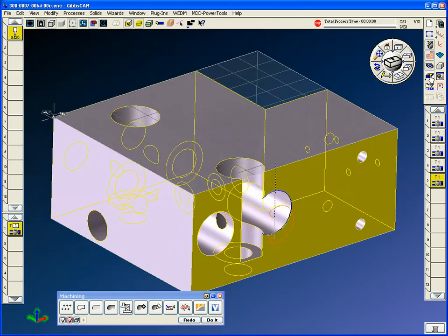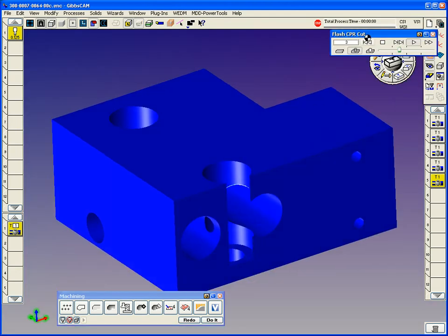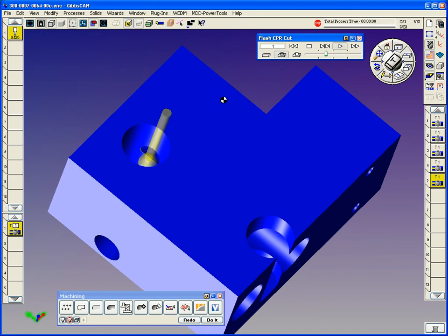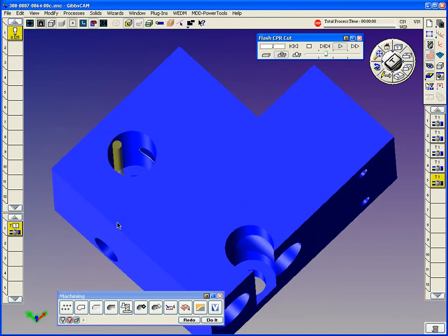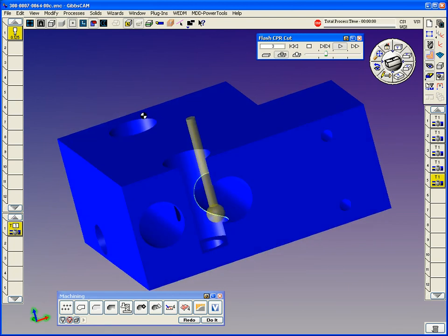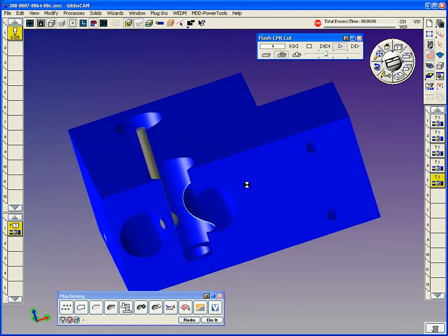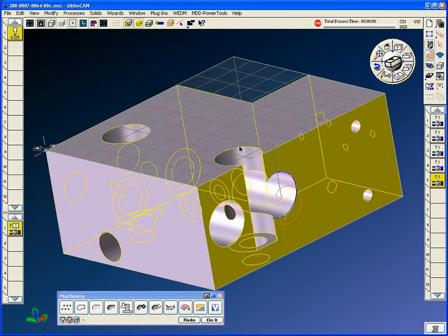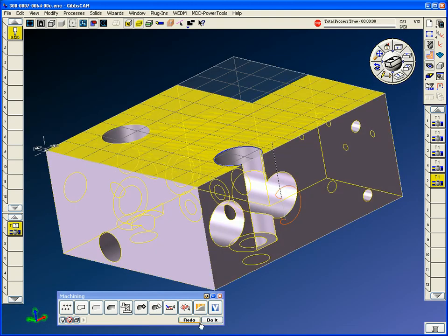It's a real slick little toolpath strategy building tool. It doesn't require much work to get it working, and you can deburr all your edges without having to do any complicated geometry creation or extracting, just using the edge and the face of any solid model. You can also click the top of this and do that, and maybe this edge.